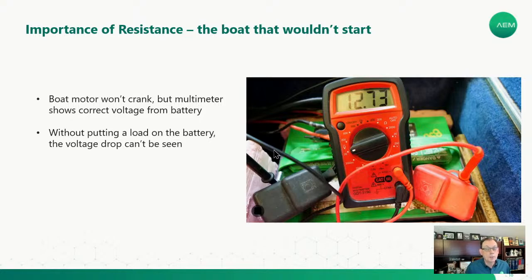But without putting a load on, we don't know that we can get that. And allocated power is simply that. It's just the switch reporting what it should be able to give you at the end of that link. So until you put a load on it, you really don't know.